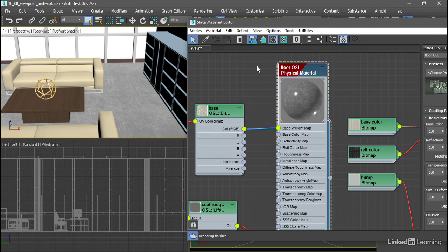It's very, very slow. Compiling the OSL to HLSL could take a very long time or just fail completely, and you will see your viewport objects display a gray checker pattern instead of a surface. So in that case, you may have to use standard shading mode, which is inaccurate but much faster. Instead of compiling the OSL script and running it, the viewport displays a kind of dumbed down, baked version of that map. It pre-renders it at some specific size, and because the image it displays is inaccurate, it shouldn't be used for design decisions for procedural maps like a noise.